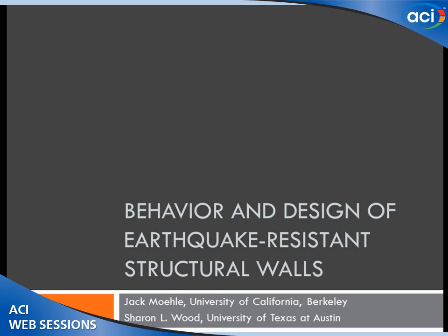No, I think it is reasonable, and to me, one of the important things this points out is the limitation of capacity design. It's an appropriate tool, but it has a limitation if, in fact, the strengths move as a function of what the deformation demands are. In the ACI building code for beams, as an example, we set the required shear strength based on the shear force that develops when the beams yield in bending.